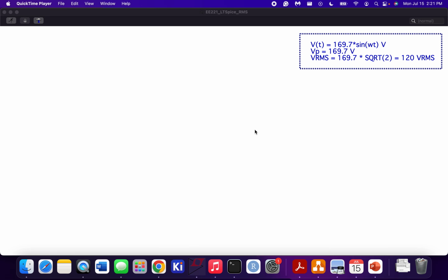Alright, so in this video we're going to take a look at how to measure the RMS voltage, or RMS value, of a sine wave. We previously looked at how to do that for an average value of a signal. I have some metrics up here that we can use just as a sanity check to make sure that our values are correct. We're going to start with a signal that's a sinusoid with a peak value of 169.7 volts. That might seem oddly specific, but the reason is that that's the wall power coming out of your outlet.